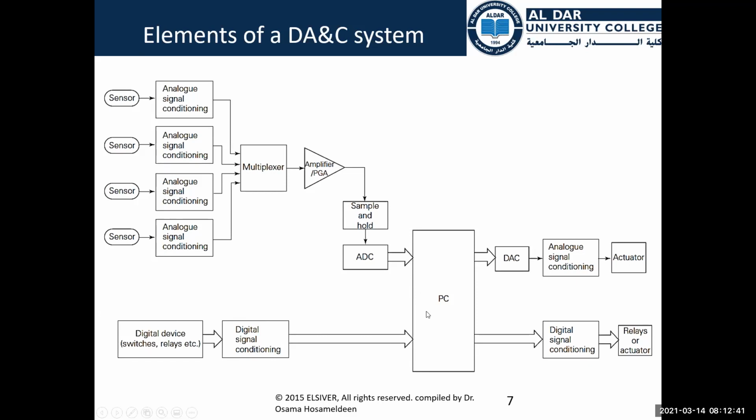Then the computer can also initiate a digital signal, which is passed to the relays or actuators immediately without the need for a digital to analog converter. You always hear about the analog signal from the outside world, then analog to digital, then getting data out from the PC, then digital to analog, and so on. But we can also take a digital signal immediately from the outside world.